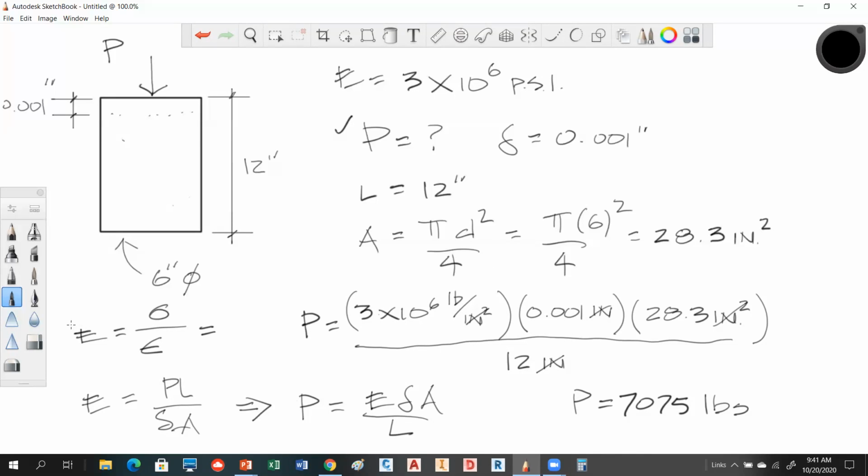This equation right here, being able to take this and bring it into something like this and then do something like this, is very, very important to strength of materials. So this interrelates stress to strain to modulus of elasticity. This is a key equation to memorize. Modulus is your stress divided by your strain, and also memorize the definition of stress, force divided by cross-sectional area, and strain, deformation divided by original length. All right. How we doing on that? Okay so far?